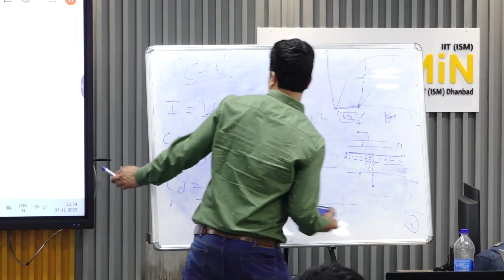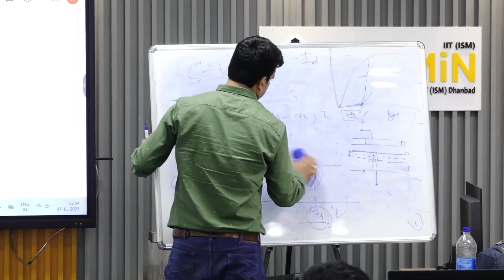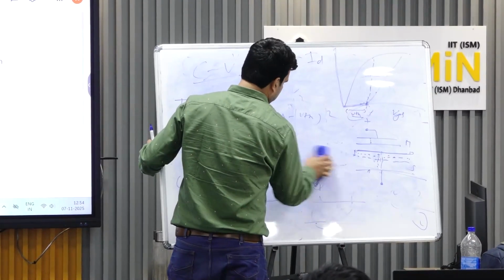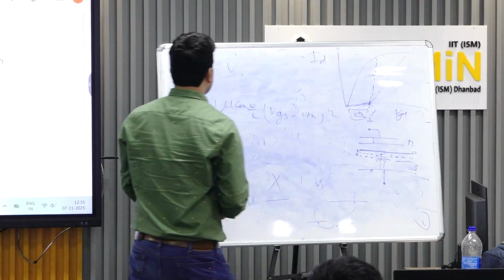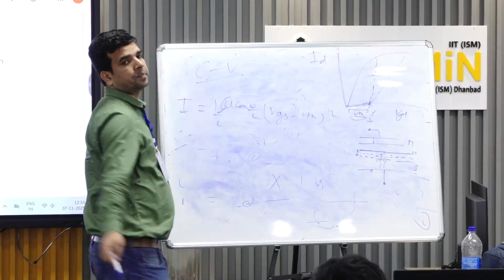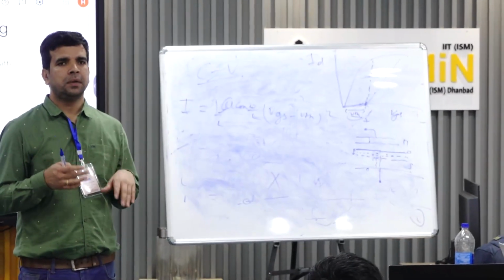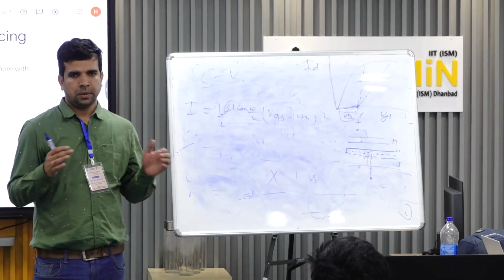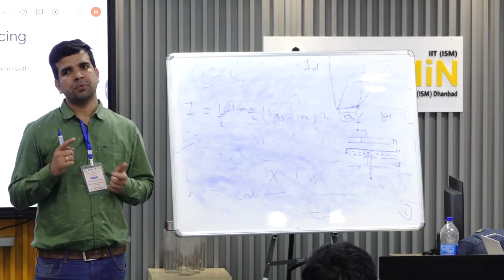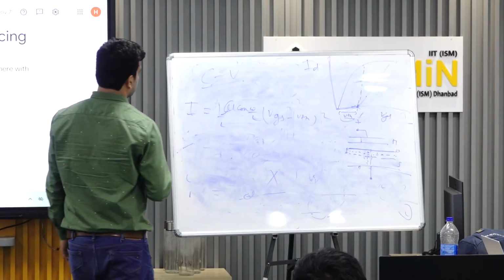Then what other things do you have to find out? Try to find all the unknown things. The second thing you have to find is mobility, which is known as field effect mobility. This mobility is what the device gives you in the presence of the total field, right? So it will be different from the intrinsic mobility or intrinsic carrier density. So you have to find the field effect mobility.